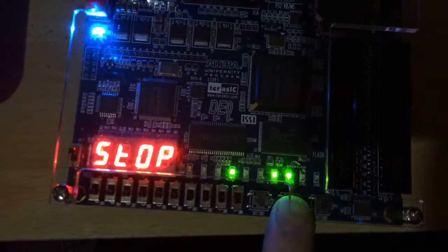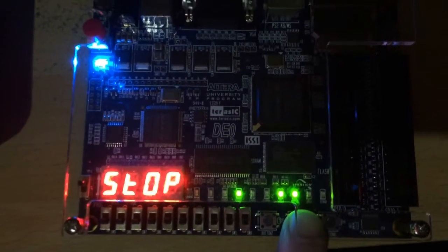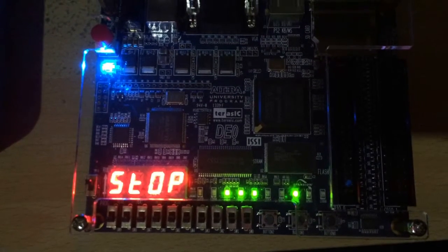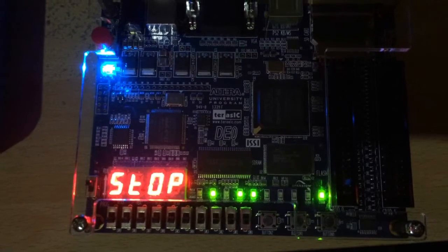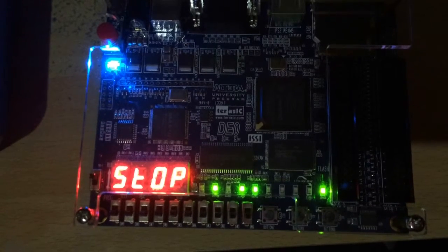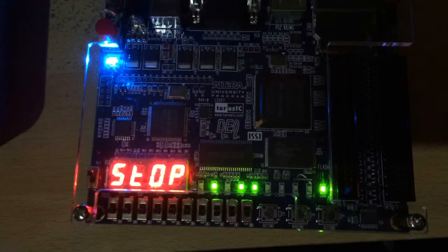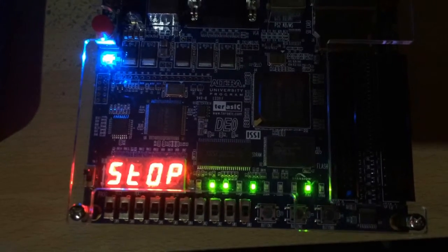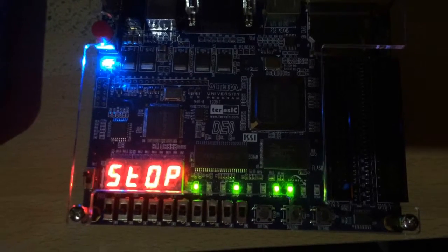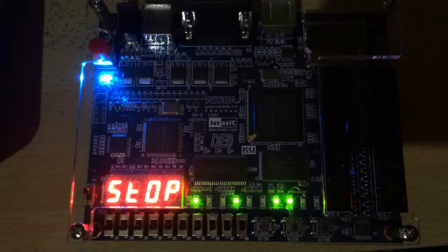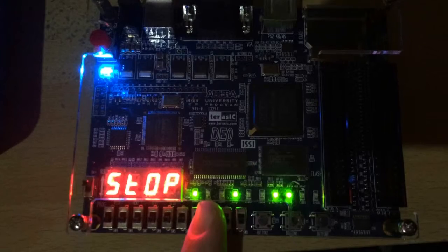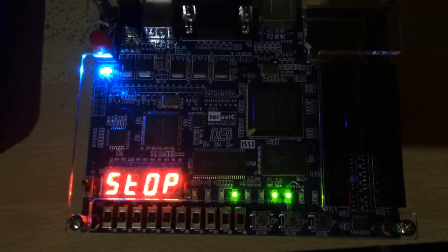So if I press key 1 here to simulate a car arriving at the minor road, we'll see that we jump into state B for 1 second, C, D, E, where we stay for 10 seconds, and once the 10-second delay is up, then we will move into state F, G, H, I, which is the same as A, only we have a 10-second delay. And then we'll move back to A in a second. There we go, state A, and that's us back to the start.